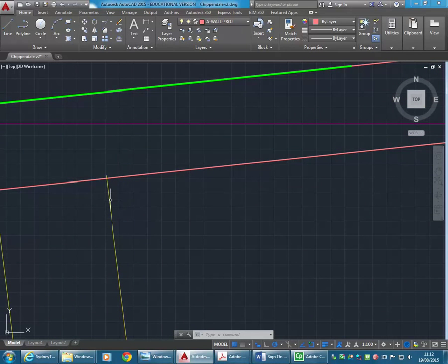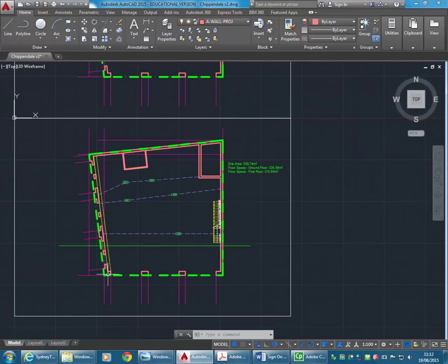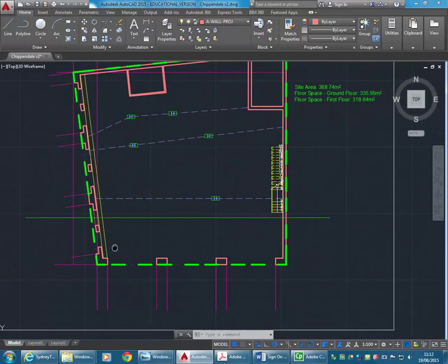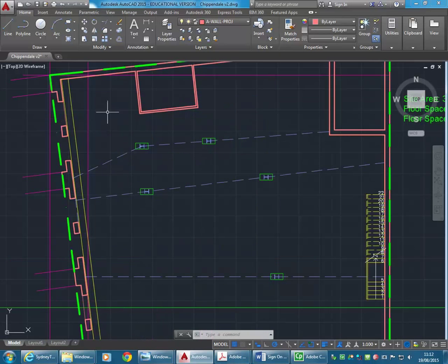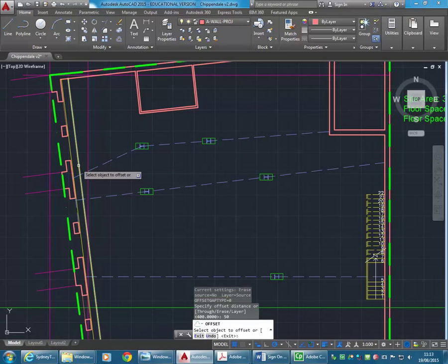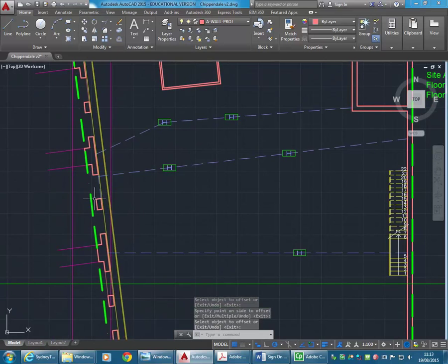Okay, so you can see it's going to stick out, and that's why you might have been thinking I could make a block for these, but it's not really an option, because the walls in old buildings are commonly like that. So I can offset 50 now to get the thickness. Now I don't need to keep doing offset over and over again.